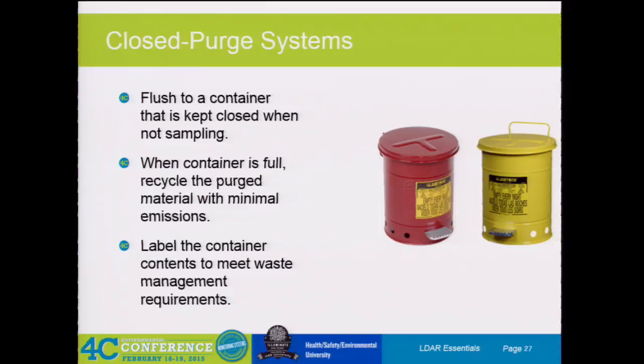So we've talked a little bit about this: closed purge, bucket with a lid. Make sure that the darn lid is on the bucket. The best is when you have the 5-gallon Home Depot buckets, or probably different at y'all's site, the little 5-gallon buckets with the lid sitting on the side. Make sure the lid goes on. And this is for every type of material, heavy liquid and light liquid. So it's not just the easy, normal LDAR mind thought of heavy liquids exempt. It's got to be closed.